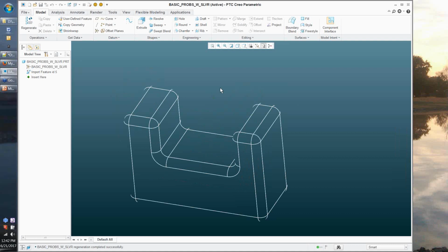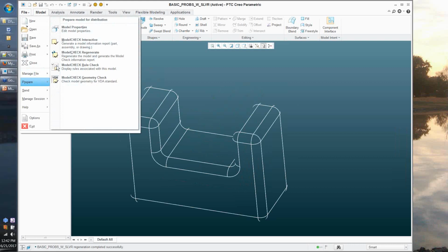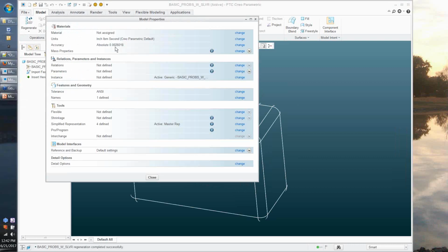If we had to go back and rematch accuracy on something I was currently working with for whatever reason, I would work to get every object in the mold scope that was part of cavity touching, and things that would be split out with volumes, matched. I'm not talking about ejector plates and the ejector house and the backers and stuff like that. The accuracy of those parts isn't as critical as obviously the stuff that touches your reference part.